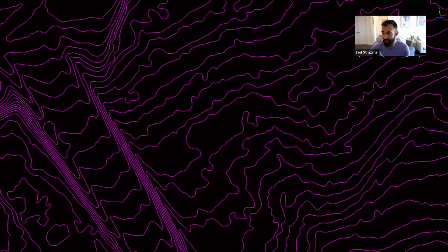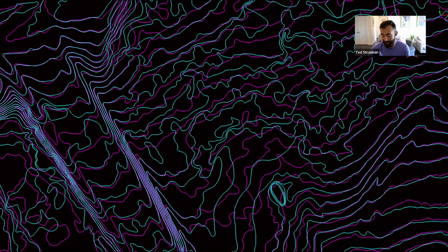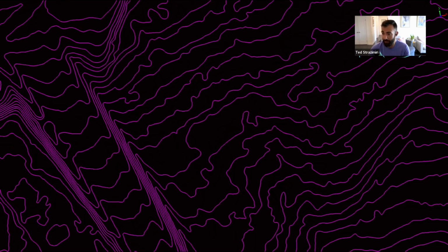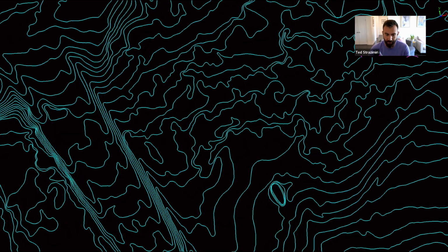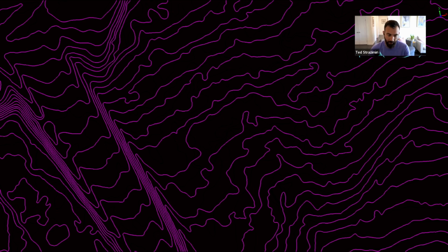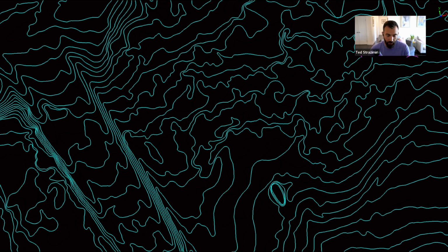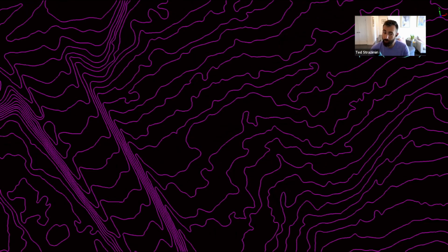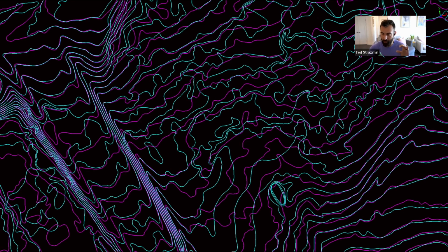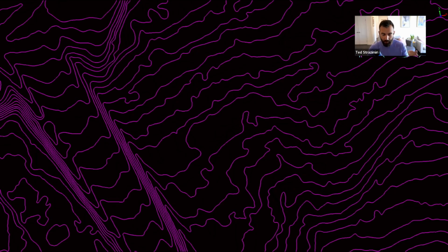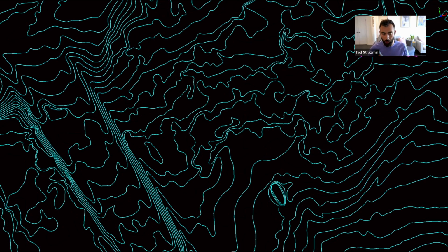Even if we went and used a GNSS receiver to shoot some points on there, is the GNSS receiver right? I mean, vertically, GNSS can be off by 2 centimeters easily, right? So when you're looking at very fine contours like this, these are 10 centimeter intervals. Even a small little undulation can make a difference. I would suspect that the contours on the LiDAR side are a little bit smoothed out, just due to the fact that the precision point to point is less. There's a little bit more gap between the points. So when the contour is being generated from that DTM, there's a little bit of smoothing occurring inherently there.